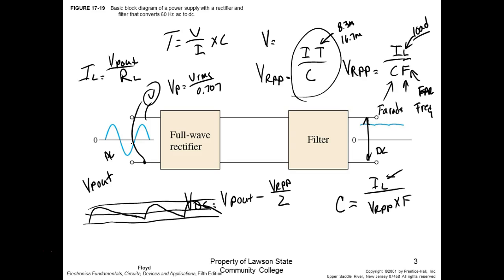Well, we could have lost the diode, right? You understand that. If we lost the diode, then any full wave rectifier, if you lose a diode, it turns from full wave to what? Halfway. So now your capacitors are going to have to run the load twice as long. So if one of the diodes opens. If the diode shorts, and that's the problem we have with solid state devices, they can short, or they can open, or they can become what we call leaky.